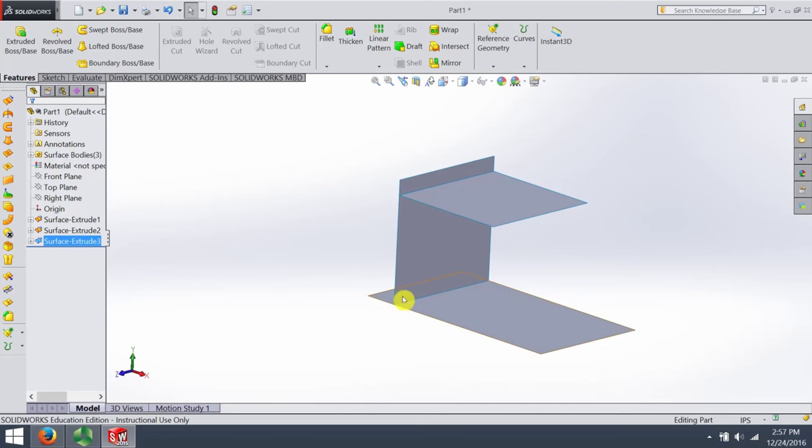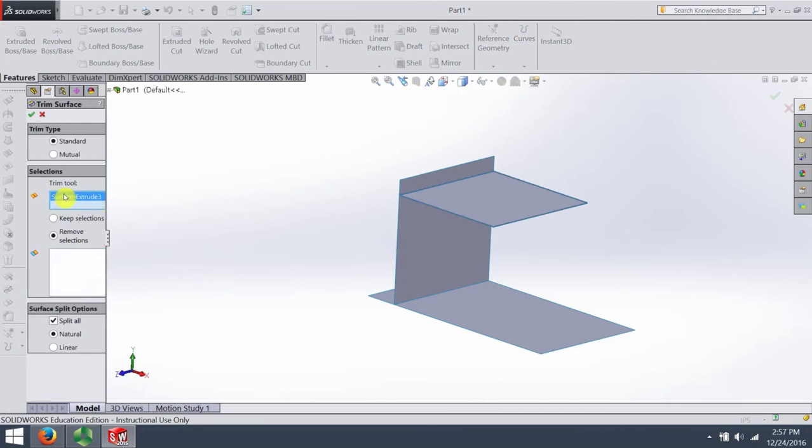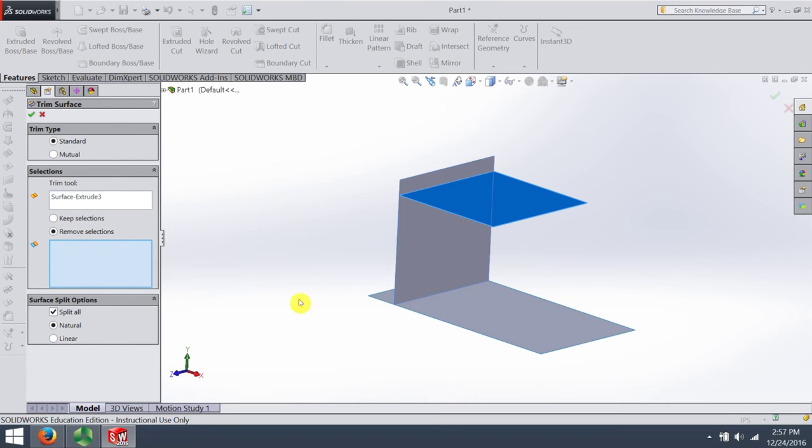So I built 3 surfaces. Now I'm going to trim off these excess pieces just so we get a nice kind of a box side to this. So I'm going to go down here to Trim Surface. It defaults to the last thing that you made, but just so you can clear this up, the thing I'm going to use as a knife, as a trim tool, is going to be in this box. So I'm going to use this one to trim off the piece above there. And it's smart enough, once you've chosen a trim surface, to toggle and be down here under the pieces to remove. So if I just go over there and grab that, it highlights. Whichever side I grab, highlights and will be gone.